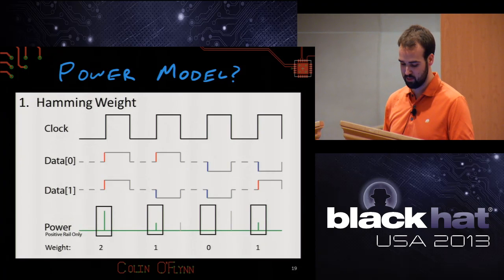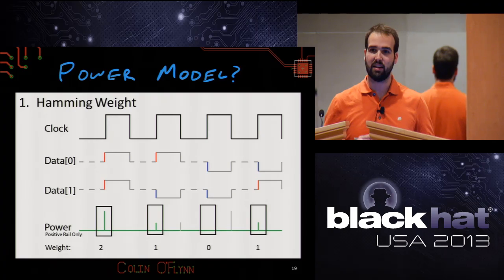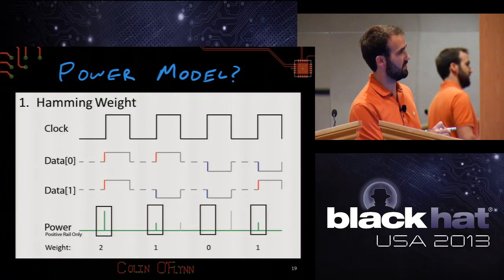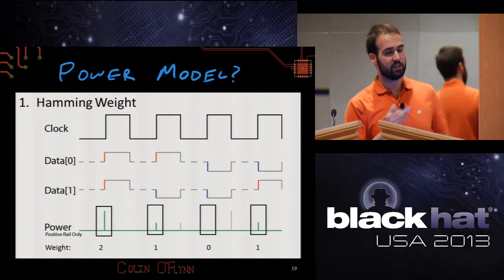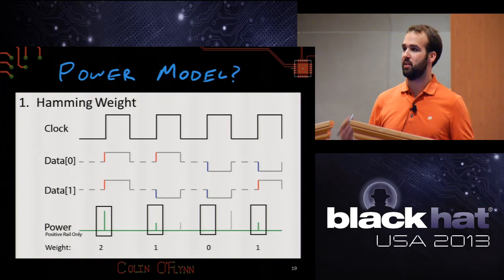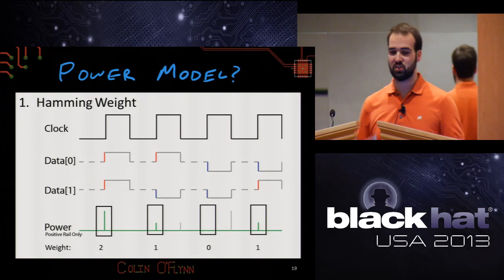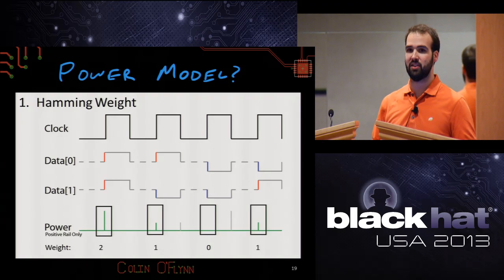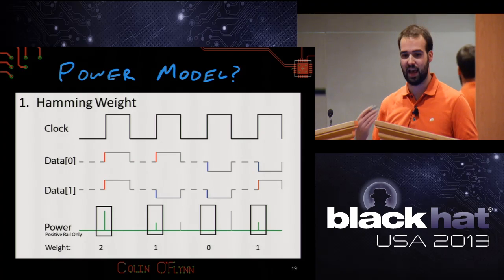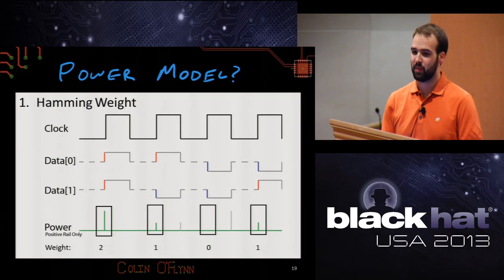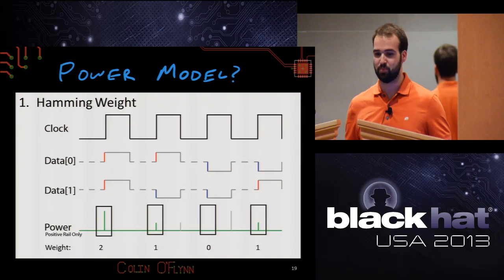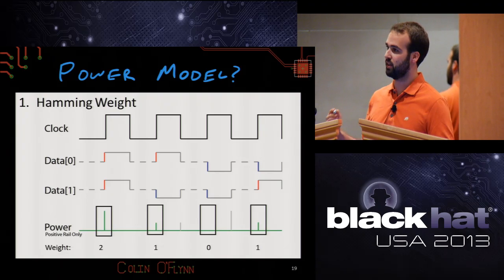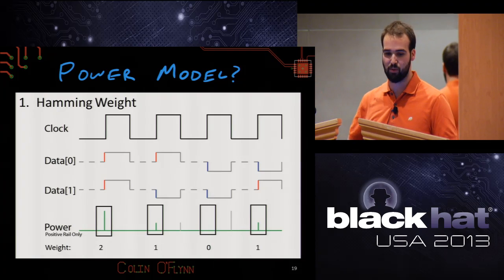So instead what they do is they always switch the data lines to a pre-charged state, which is effectively this intermediate middle state here in dashed lines. This pre-charged state is halfway between the 1 and the 0. The point being that when you want to switch the data lines to the 1 state, you no longer go from 0 to 1 potentially. You always go halfway to 1. So it's half the required power. So your worst case scenario is now much better than when you're switching all the lines from completely 0 to completely 1.